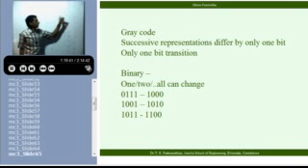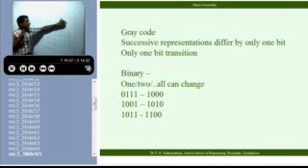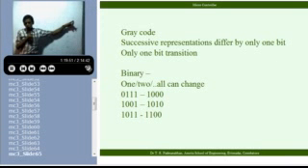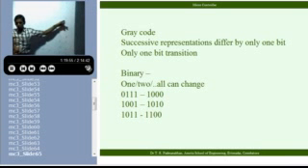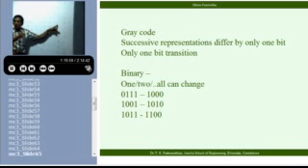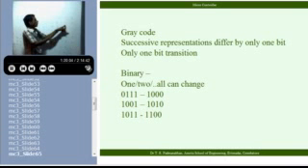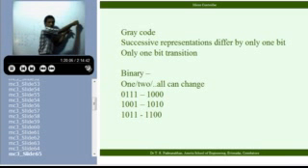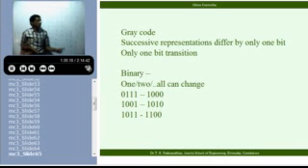Alright? Having done that, for the next one, I can accommodate only one change. I would like to do it with a minimal number of bits. I make this fellow 0. Alright? I go ahead. From this combination, I have to put one change. I have done whatever I can do with 2 bits. So gray code with 2 bits will stop here. If you want to go beyond that, you have to go for the 3rd bit.